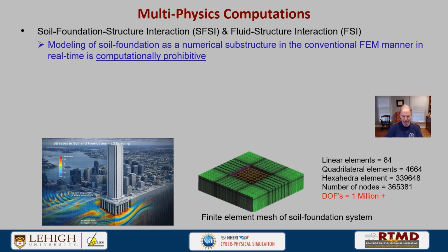Multiphysics computations are very challenging. Shown here is a soil foundation structure interaction, and I'll talk next about fluid structure interaction. In terms of the former, the modeling of the soil foundation system as a numerical substructure using the conventional finite element method, particularly in real time, is computationally prohibitive. You can see here the number of degrees of freedom for this particular foundation, over 1 million, because of the number of elements and the number of nodes associated with that system.